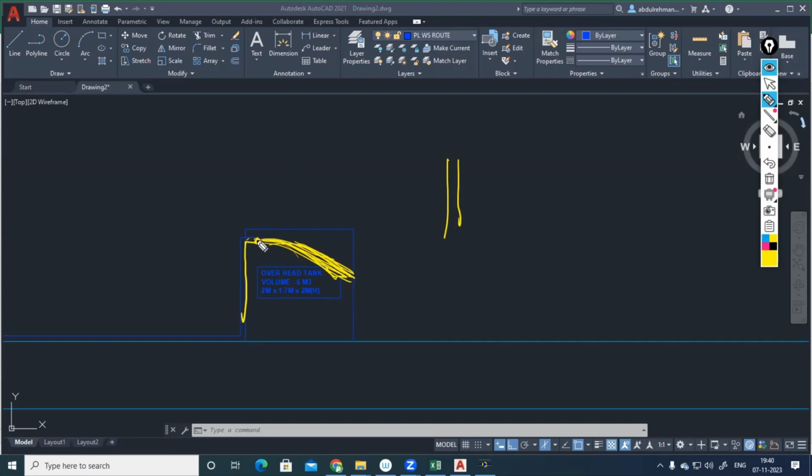How can we avoid that? See, when it is coming there, the pipe will be coming from the bottom like this, then entering there. There you can provide a T-joint like this. So water will be flowing downwards rather than going this way. Then after the T-joint, we will be slightly extending the pipe. Then we can propose an end cap there. By the help of the end cap, we can close it. Otherwise, if your pipe is coming there, you can propose an elbow. If you are proposing an elbow there, water will be flowing down only, not there.